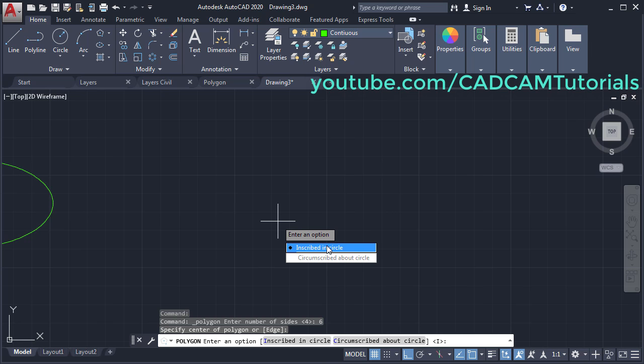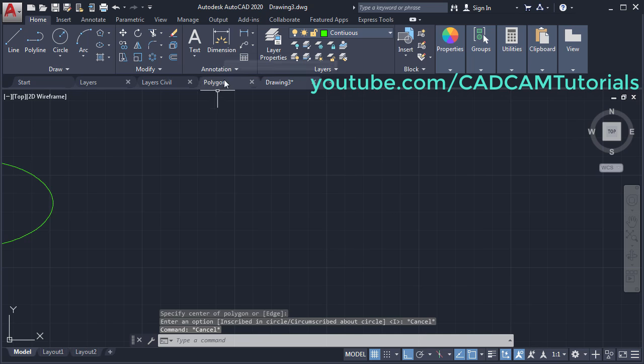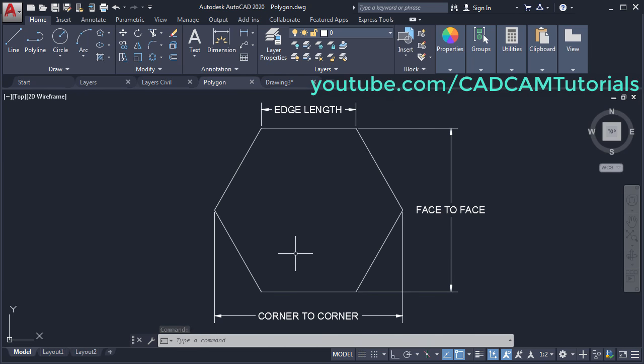I will just press escape. And here is the polygon. So polygon dimensions can be specified in three ways. You can specify the distance between two parallel surfaces, that is face to face, or you can define the distance between two opposite corners, that is corner to corner, or you can directly specify the length of any one edge. In these three ways, a dimension can be given for a polygon. So any one dimension will work.